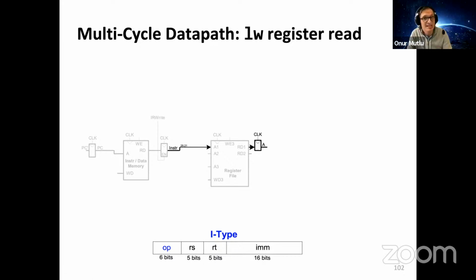So in the next clock cycle, we're going to use the data inside this IR instruction register, let's say, and use it to ID the register we're reading, access the register file, get the data out, latch it. That's our clock cycle again. Somehow we determine the clock cycle and we say we latch it at this point. In the next clock cycle, we're going to just read the register. Okay? And this is microarchitectural state 2, if you will.